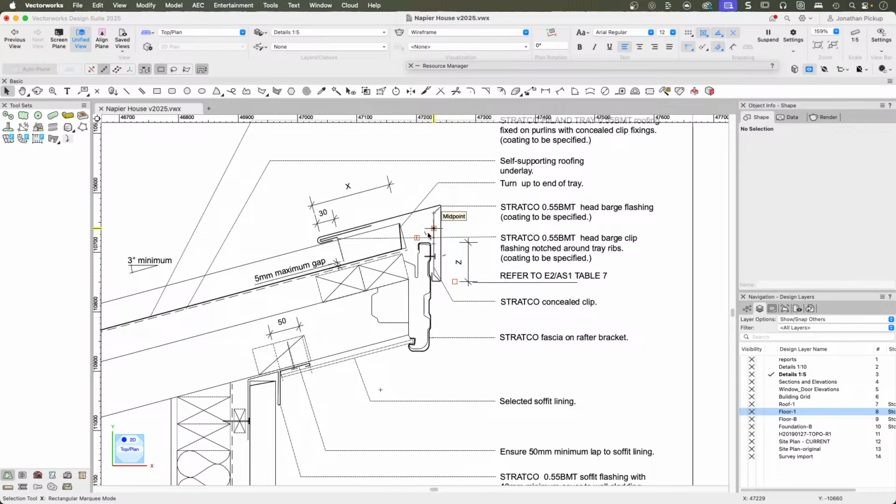I need to study these. Now, if you're going to create your details, you have to remember the way that we have to keep water out of the building. Now, there are 4 main parts of detailing and 5 physics principles we have to look at. Number 1, the 4 Ds of detailing: deflection, drainage, drying, and durability.